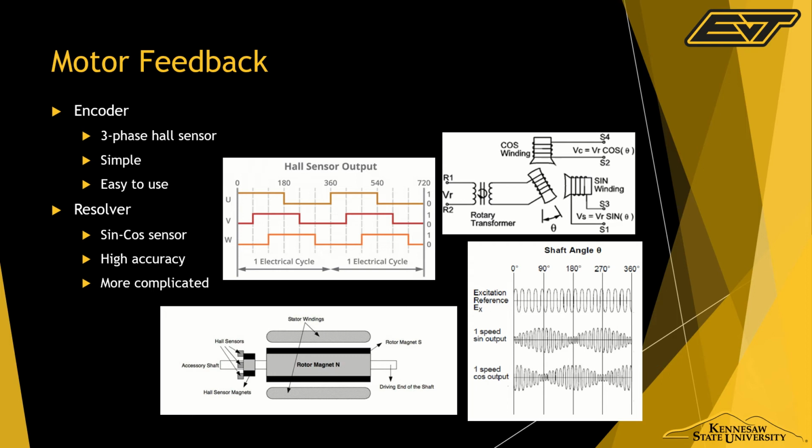If for whatever reason the motor controller freezes for a microsecond, which is entirely possible, given EMF, communication errors, and other things like that, and then it just doesn't read one pulse from the motor, now your motor is offset from what the motor controller is delivering to it, which then results in lower efficiency of the motor. So it's better to get absolute position using three phases or more.